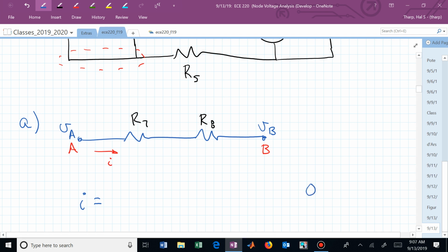Here we're just applying, I shouldn't say just applying, because Ohm's law is important. We are applying Ohm's law. If we want I being directed from left to right, then we need to know the potential difference, or what's the voltage dropped between node A and node B in terms of these labels.